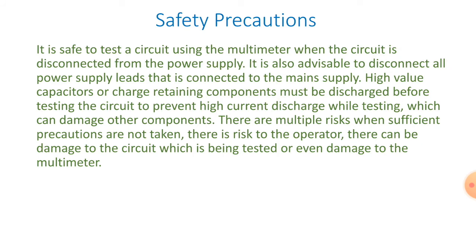Safety precautions. It is safe to test a circuit using the multimeter when the circuit is disconnected from the power supply. It is also advisable to disconnect all power supply leads that are connected to the main supply. High value capacitors or charge retaining components must be discharged before testing the circuit to prevent high current discharge while testing, which can damage other components. There are multiple risks when sufficient precautions are not taken. There is risk to the operator. There can be damage to the circuit which is being tested or even damage to the multimeter.